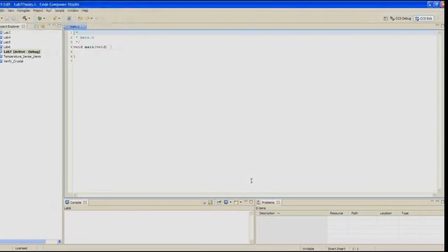In this lab exercise, we're going to be building a program that transmits the ASCII characters HI, high, or low, or in, using the software UART code. The 2231 does not have a hardware UART on it. The 2553 does have a hardware UART on it. But in either case, it'd be more interesting to use the software UART code just to show you the way that we are able to take example code, easily drop it into our system, and build a new set of software. So this data will be communicated, the high, the low, or in, through the USB COM port and then onto the PC for display on a terminal program.